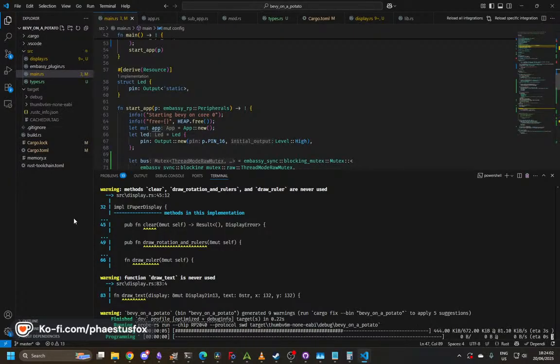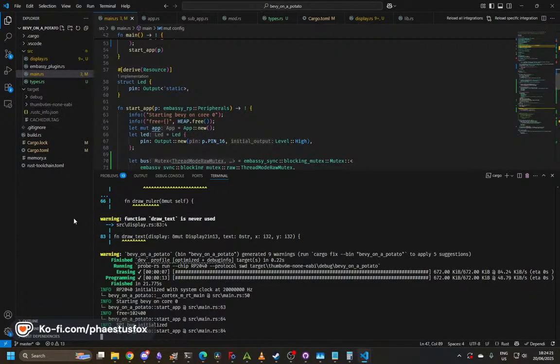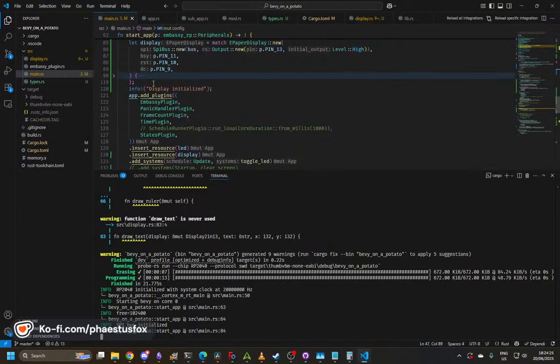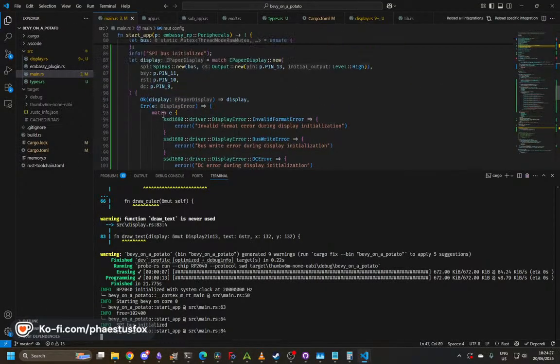The 5-volt and the ground are not very well separated from each other, and they had hot glue on them to keep them from touching. But that's come off, and they probably touched, but not enough to kill the chip. Probably not good for my computer, shorting them to ground. But anyway, SPI bus initialized, but the display never initialized.